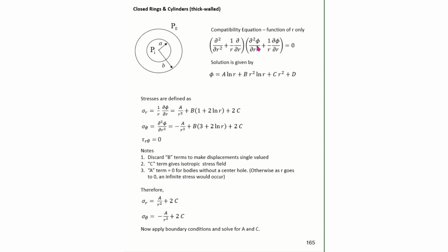On this slide, we show here the expression that governs the stresses in a cylindrical element or cylindrical axisymmetric type problem. This expression here is derived from equilibrium and compatibility equations. And compatibility equations are what force displacements to be equal. We see that in this system we are solving for phi, and phi is the Airy stress function.